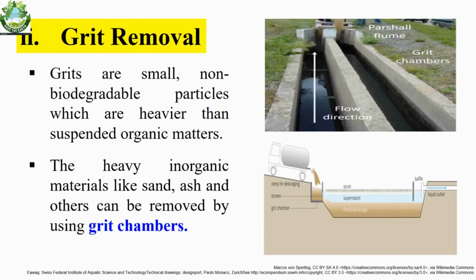These can also be used with screeners, and they may be kept either before or after the screeners. So due to these screeners and grit chambers, the solid particles can be separated out from the sewage wastewater.